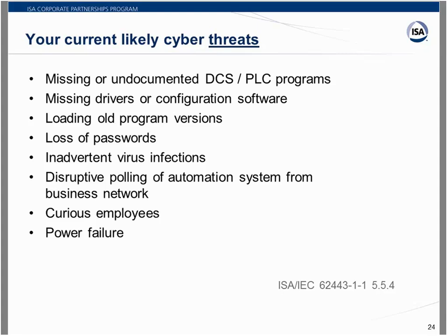And then lastly is power failure. You know, if you have a power failure and you don't have the right battery backups or you haven't maintained your battery backups, all of a sudden that will show that you have missing PLC programs, missing drivers, you've lost your passwords. All those things happen after a power failure because you weren't really paying attention to just the power going to the units. I've surveyed several locations that when I've tested the backup power, none of it's worked. And even when I've asked to have it fixed, it hasn't been fixed for up to years.